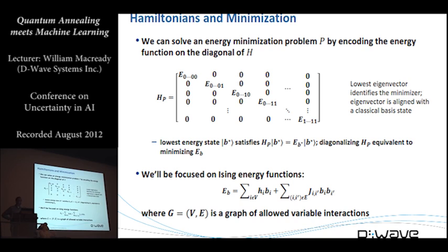And in the hardware that we're developing at D-Wave, the kinds of energies that you can put along this diagonal are Ising models. They're actually a restricted kind of Ising models, but they are Ising models. So all these parameters, these h's and j's, for the linear and coupling terms that you can describe between bits, are user definable. There is a significant constraint, though: because, as you'll see, these qubits actually have physical analogs in a piece of hardware, you can't program interactions between all pairs of qubits. Only certain of them can you have programmable interactions, and for the remaining qubits, of necessity, the interaction has to be 0.